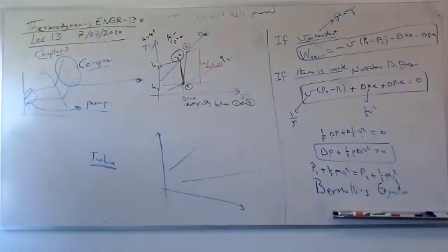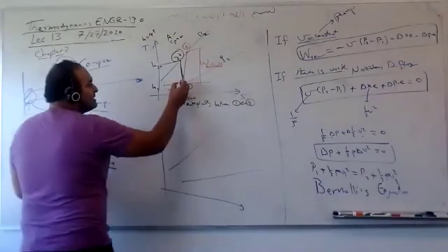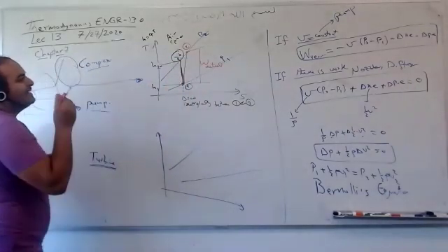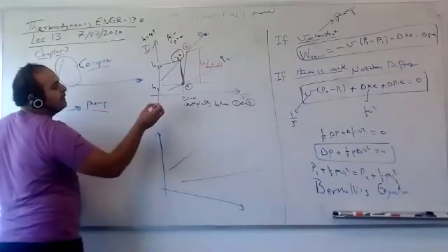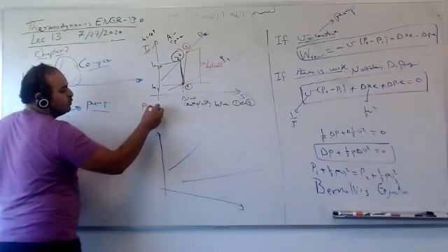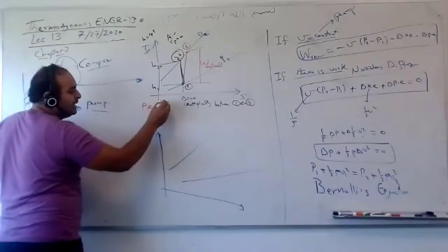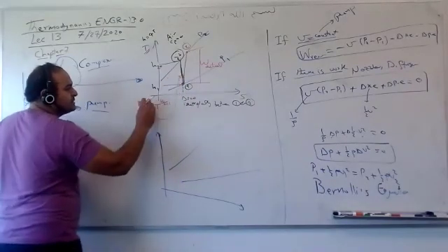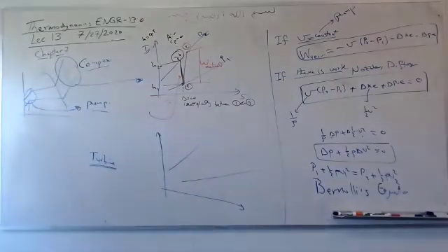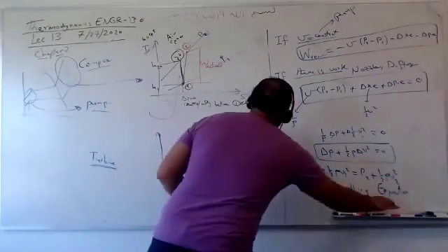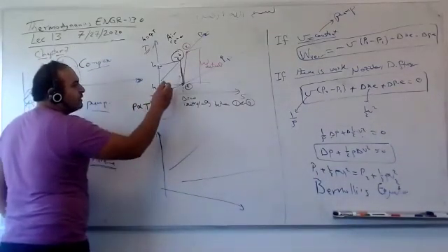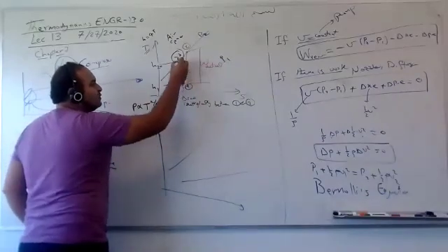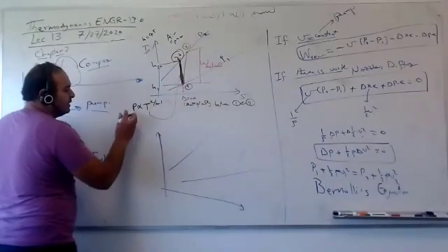So we wish to go vertically from 1 to 2S. Remember, for 1 to 2S, we can use the isentropic relation. For example, T and P can be related, like P proportional to T to the power K over K minus 1, only along this line. Let's look at the black line, the isentropic line: P proportional to T to the K over K minus 1, only along the black line, because it's isentropic, delta S equal to 0, from 1 to 2S.